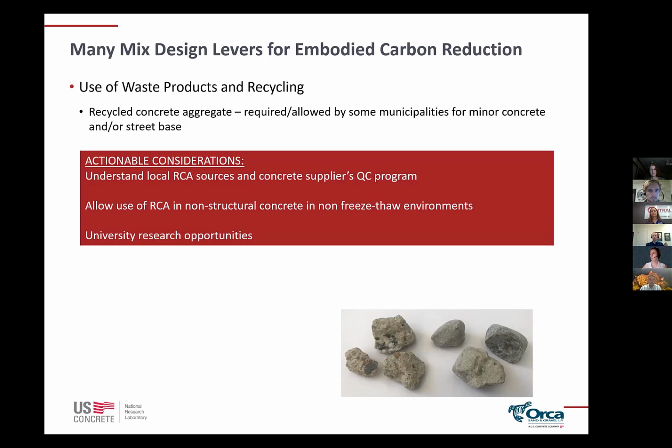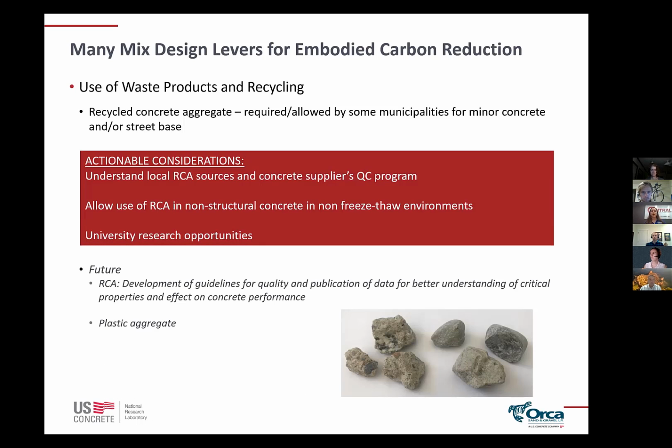Something I will say is that I am familiar with there being challenges in freeze-thaw environments with durability. And so it's not that it can't be done there, but that's something to be aware of and talk to your ready mix producer about. And then with this, I think there's also university research opportunities.